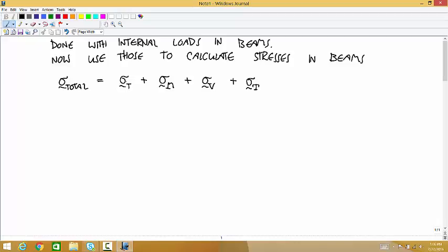So you might think, rightly, well, maybe material that's under tension compression behaves differently in bending than it does if the material isn't in tension compression, right? I mean, there are these complicated interactions going on. But our ability to break it up into the sum of individual internal loads is called the superposition principle. It depends on the linearity of the relationship between stress and strain and on small deformations. So it's not true in general, but it's true in this class and in most analyses you'll have to do as an engineer involving stresses and strains.